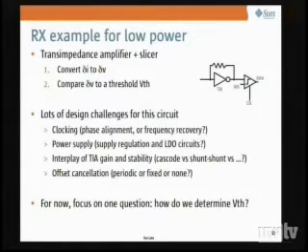But rather than getting into all these questions, let me just focus on one question, which is sort of interesting: how do I determine what VTH is? That's a threshold, right? I get a small voltage out of the TIA. I've got to compare it with a reference to say whether it was a 0 or a 1. So how do I pick the reference?